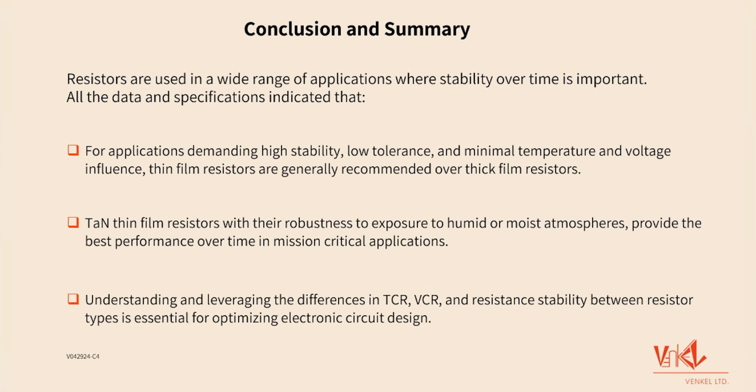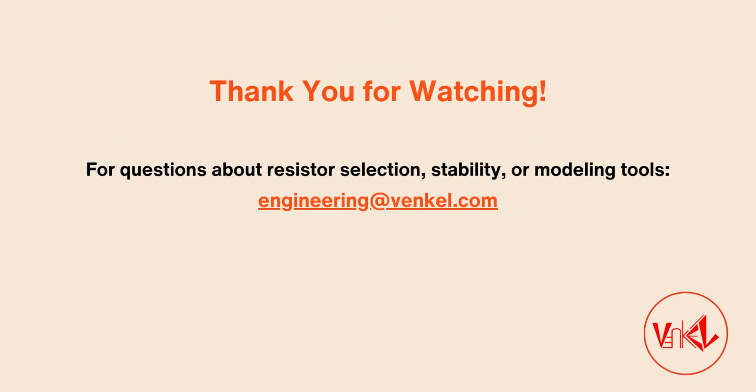For environments where exposure to humidity or moisture is a concern, tantalum nitride thin film resistors stand out due to their robustness and resistance to environmental degradation. This unique capability ensures long-term reliability even in mission-critical applications requiring exceptional stability.